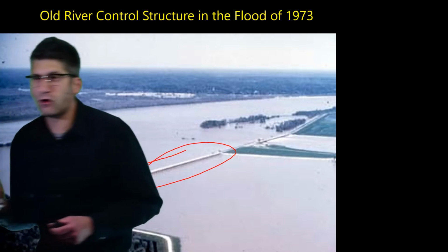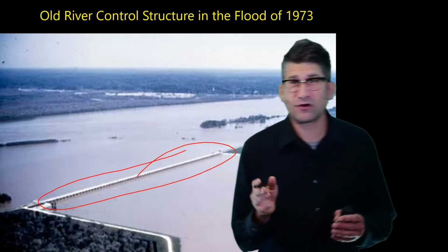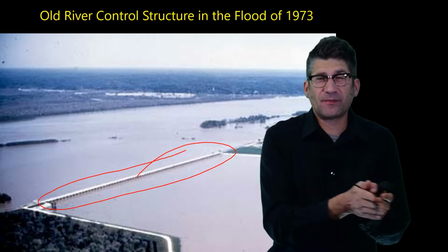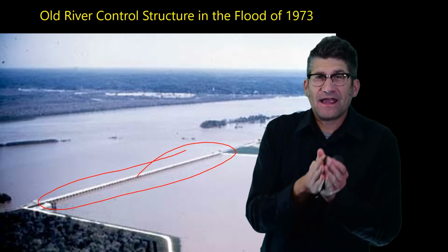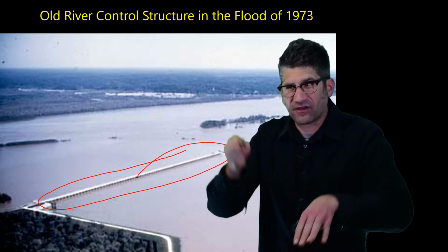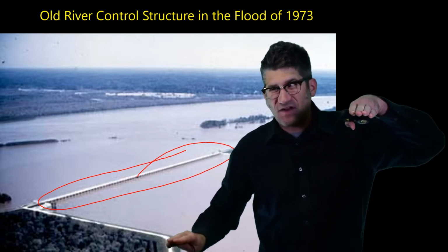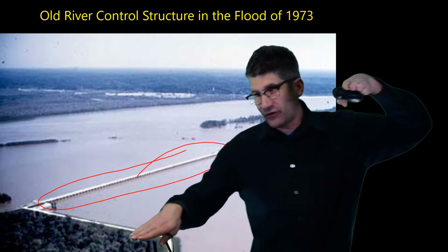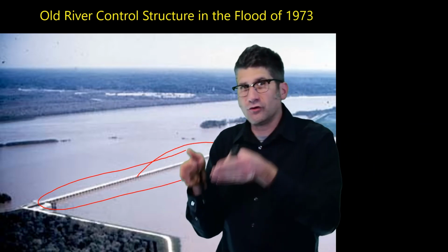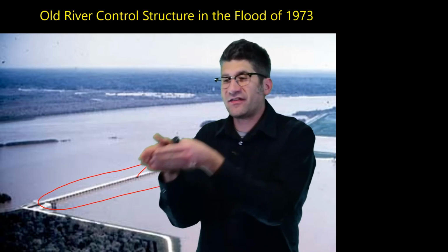This is all that holds the Mississippi River from abandoning its current channel that will take the Mississippi by the city of New Orleans and entering a lower pathway, which is the Atchafalaya River. The Atchafalaya River is sitting 5 feet lower than the Mississippi. So if you're able to dump the Mississippi down in, it's going to erode and you're going to lose the majority of the flow into the Atchafalaya.